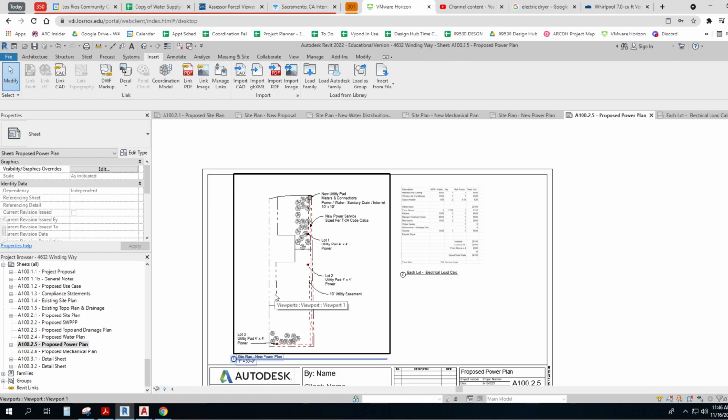You can. You just have to do a little bit more work on that roadway to make sure that it's well compacted and that everything is at a certain depth so that as you drive over it year after year after year, you don't damage something due to settlement.